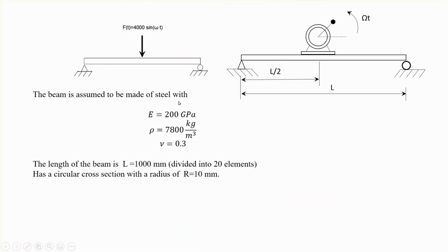So suppose you have a bar, or a beam as shown below, with a given cross section, and it's simply supported, as you can see. And right at the middle of this, or somewhere else, it doesn't have to be the middle, there is a sinusoidal load that is acting. If you think, how could this be true? Well, imagine that there's a motor turning at a given speed, and there's an unbalance associated with the motor, which is always the case, and therefore there's a sinusoidal, harmonic load that is applied at the middle point.